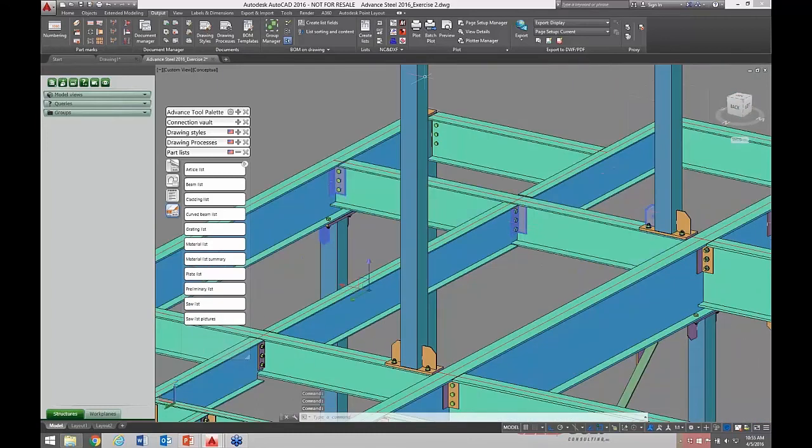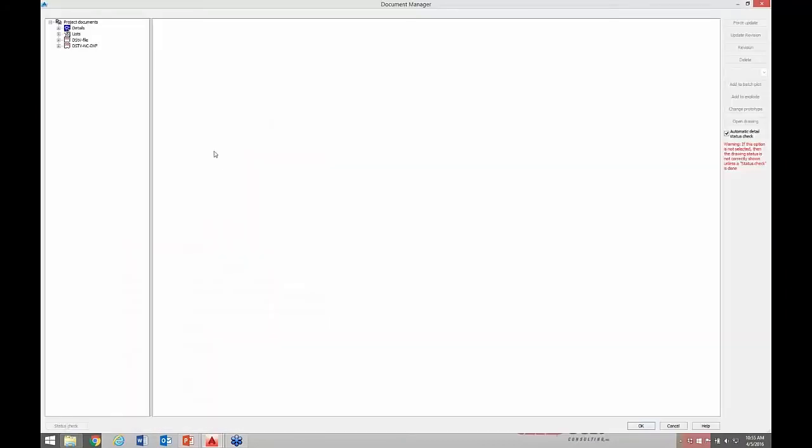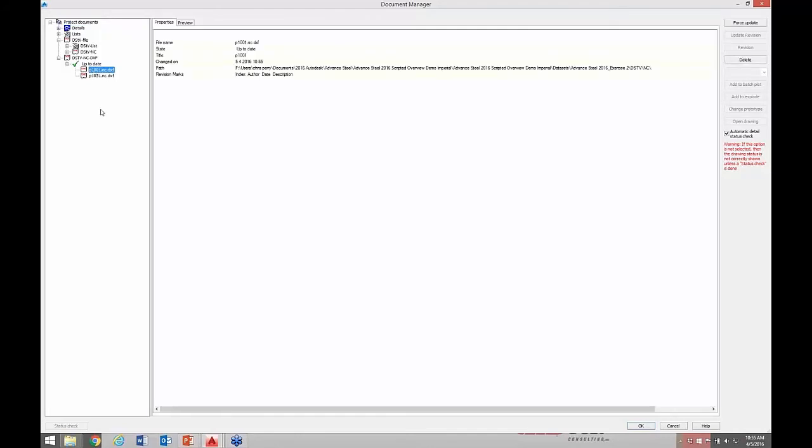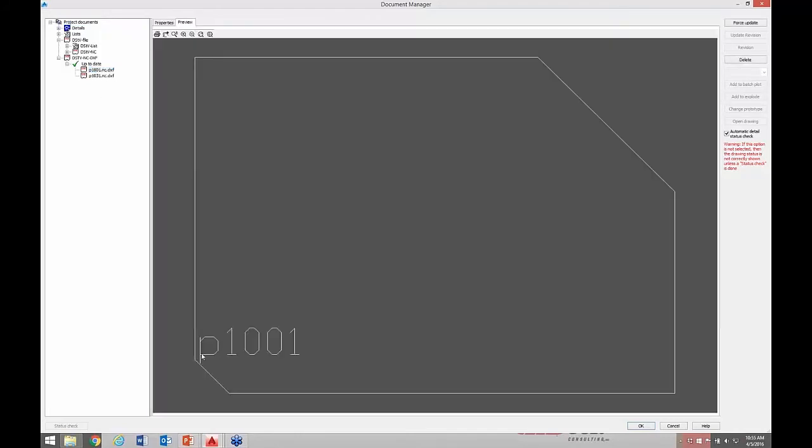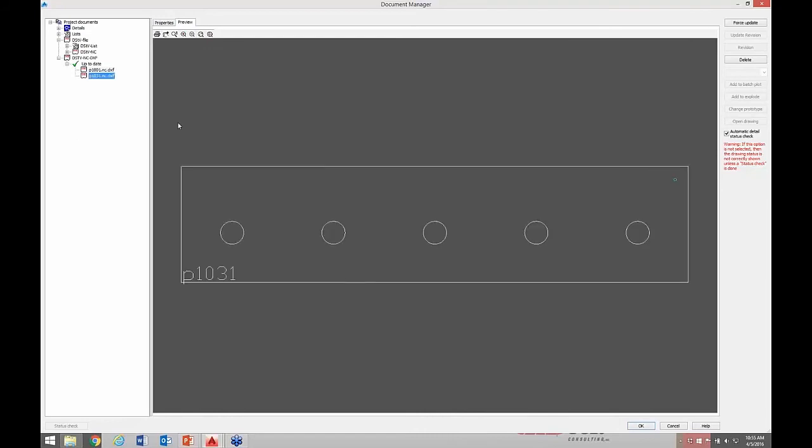And we're actually going to generate some DXF of those selection plates. It tells me very quickly they've been created successfully. While I'm here, I'm going to go ahead and create the NC files, getting that ready for my extracts. And then I'll go back to my document manager. We can look in those areas. As far as our DXF files go for the plates selected, there we see, even with the piece mark, for those couple, I had similar ones that I had selected.